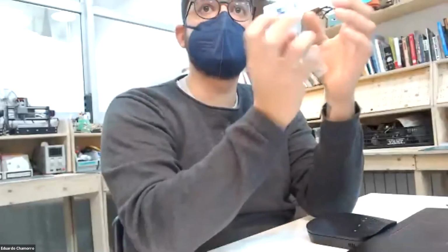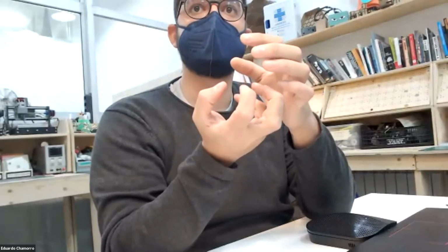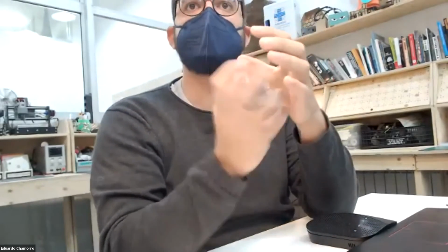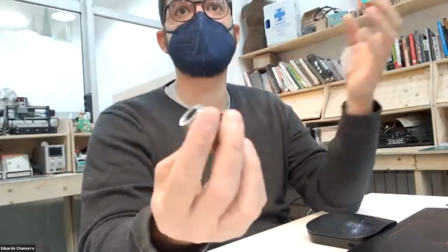What's the issue if you hold one too strongly? You can damage a little bit the thread on the motor while tightening, because it's pressed a little bit too much and doesn't come out as smooth, and the threads of the motor are expensive. So trying to save like 20 euros against a 3K or 5K motor really doesn't make any sense.